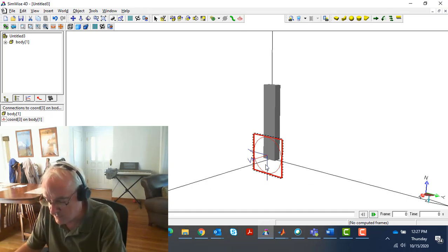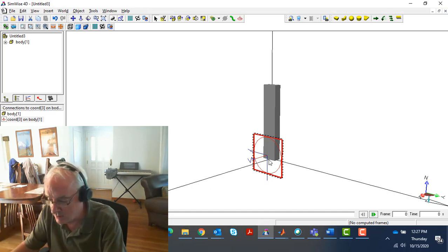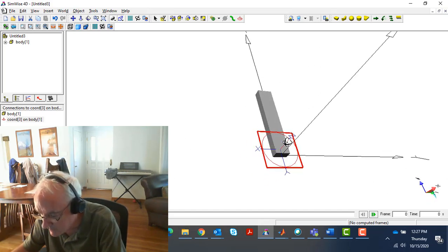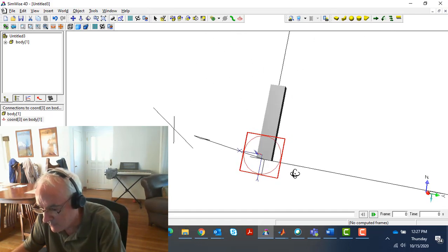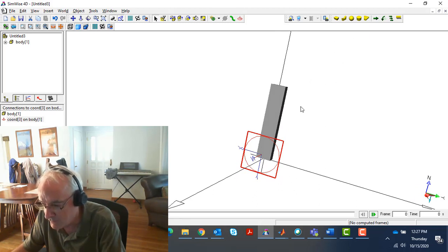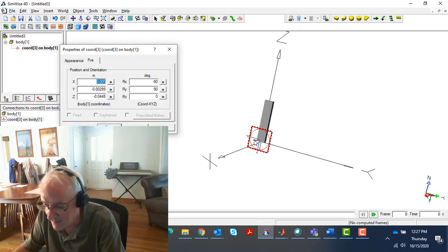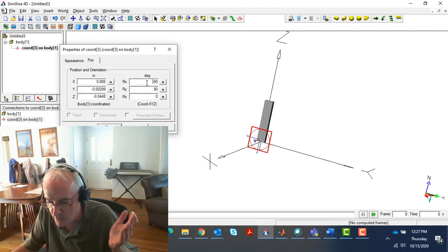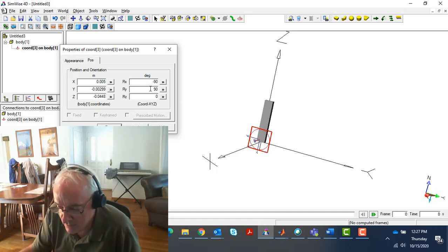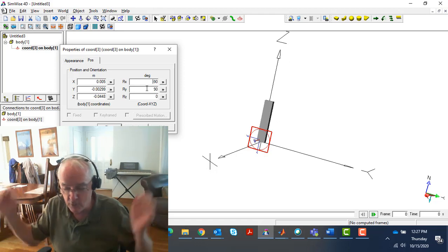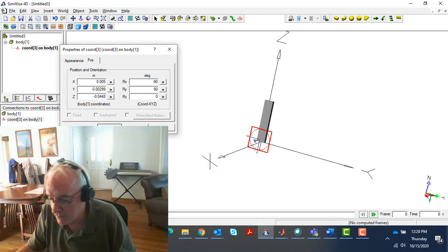But it's essentially a representation of location as well as orientation. And you'll see that little XYZ coordinate system showing up on that surface as I placed it. And notice it's a little bit out of rotation with my global ones, which is the black ones. And that difference is actually expressed quite well by these Euler angles. So a rotation of minus 90 to 90 on X and Y, and these things called Euler angles, will set that orientation relative to our global coordinate system.